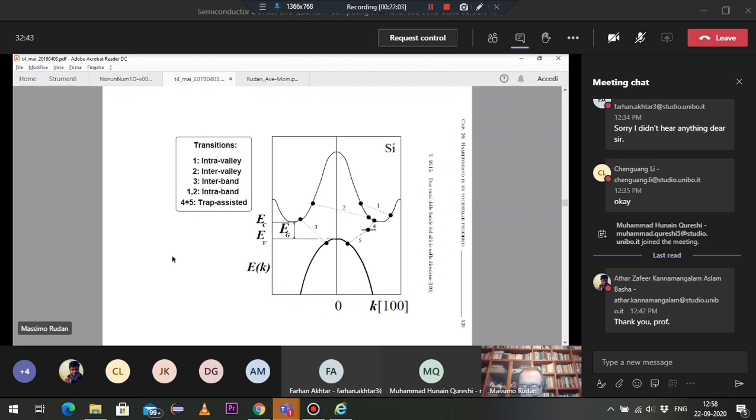In conclusion, out of the infinite bands in a semiconductor, or more generally in a crystal, the only bands that are able to contribute to the electric current, and therefore are of some interest to us, are those that are partially filled, meaning that some of their states have an electron in them and some other states do not.